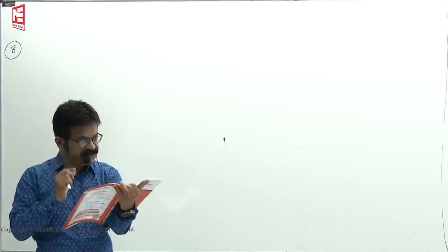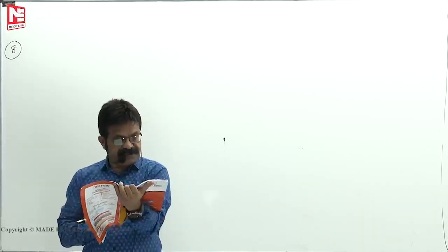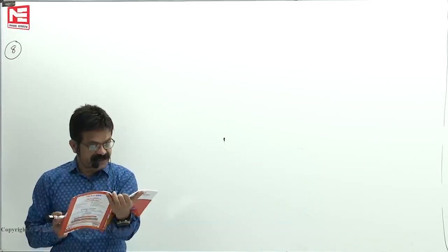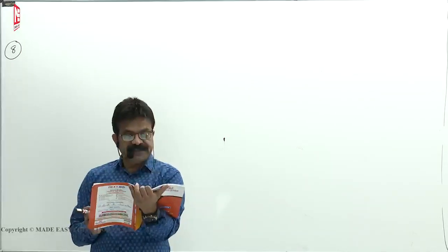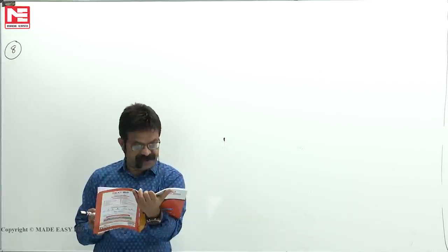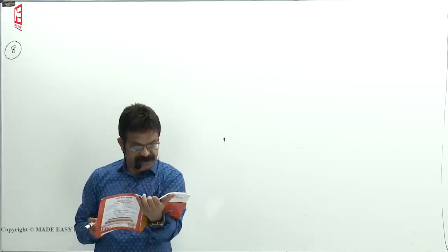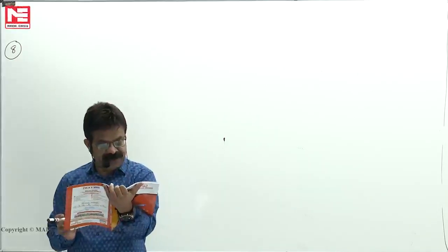Now you see we have a 3-hinged stiffened girder suspension bridge. The total span is 120 meters and it is subjected to 2-point loads, 240 and 300, at distances of 25 and 80 meters. If the suspenders are transmitting an equivalent UDL of load Q naught kilonewton per unit length, the value of Q naught is?